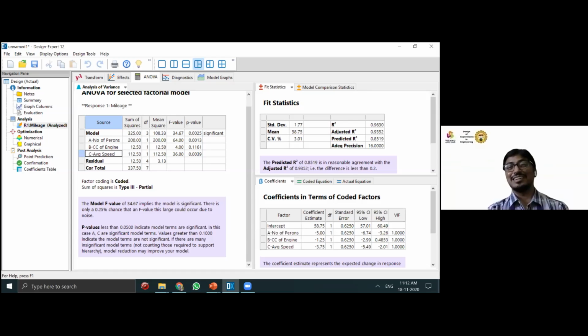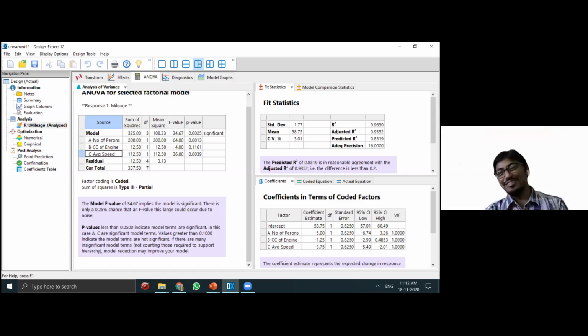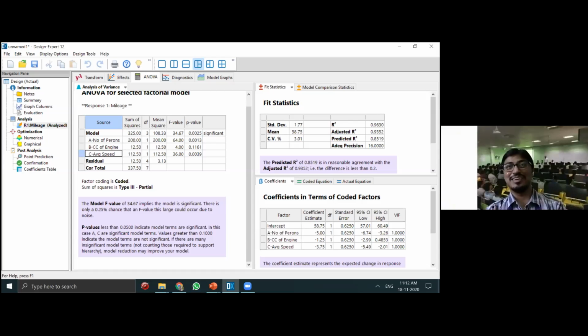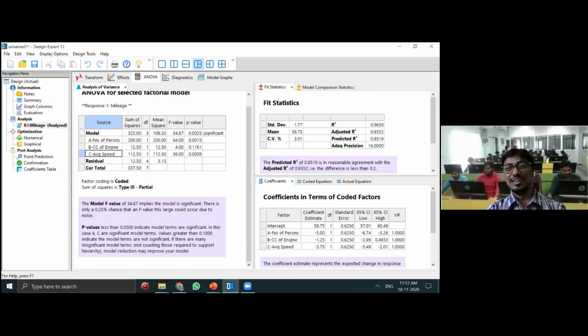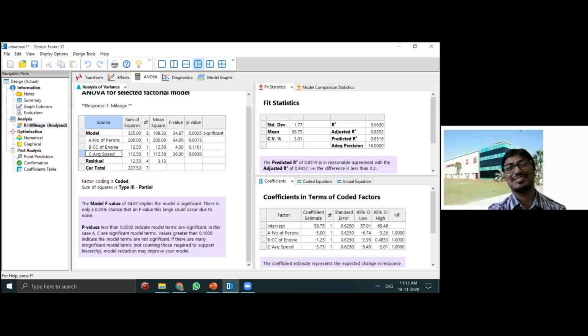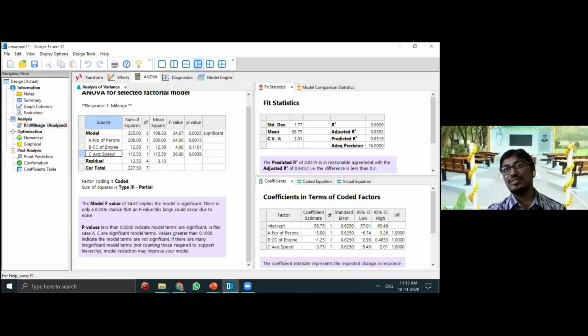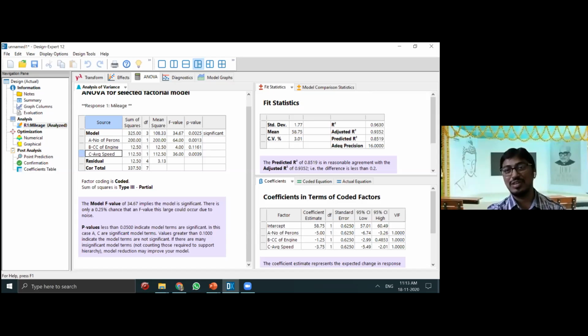So everything is interrelated, like Six Sigma, right? When we consider Six Sigma quality checks, from the raw material till the final product, every step has to perform to 100%. So this is the issue. In most experimentation, we get the data and have done the experimentation with the design, but when you come to the ANOVA, your R square and adjusted R square will not be above 0.9. If you have done it very carefully, then it should be above 0.9, and this should also be above 0.9.